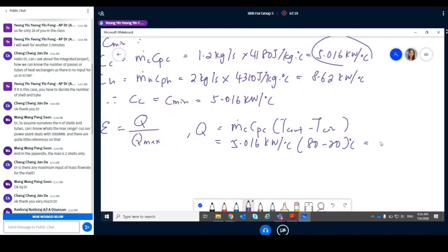Both can, but the equation will give you more accurate results, because the value from the chart is actually calculated from the equation. All right, and then you need to check what type of heat exchanger it is: a counterflow double pipe. So counterflow double pipe, like this.